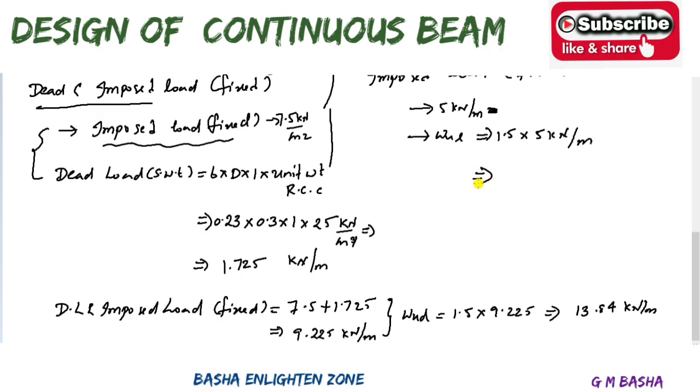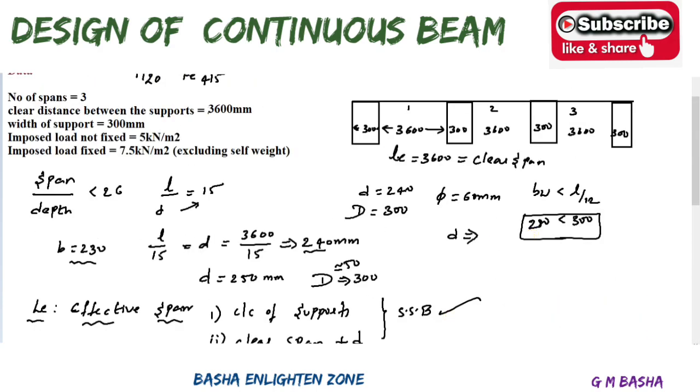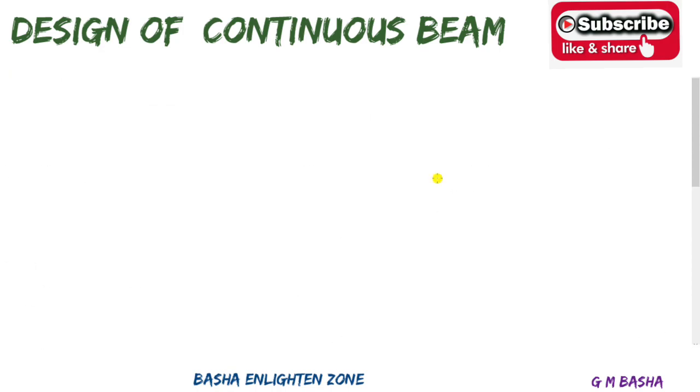If you simplify, how much will you get? You will get around 0.5 times extra, that is 7.5 kilonewton per meter. So this is the way to calculate dead loads and live loads individually. First see the given data, and based on that, according to the code, you can adjust your dead load and live load. Then this is your dead load and this is your live load.